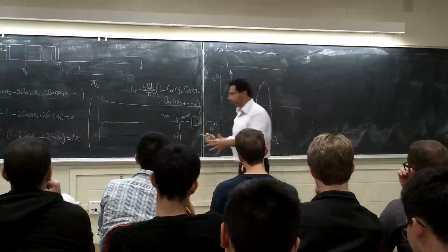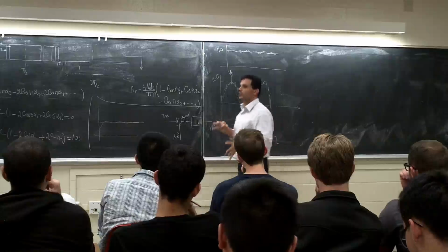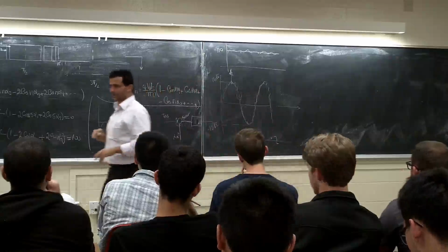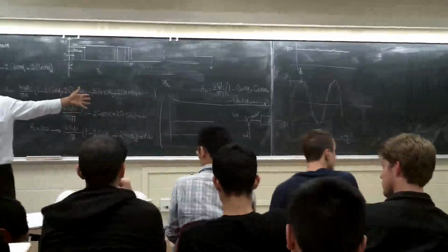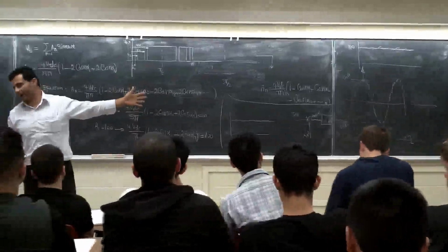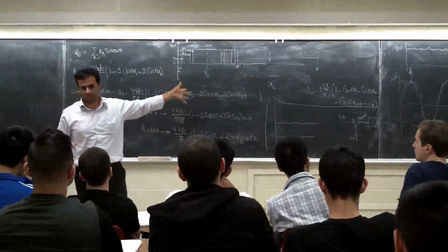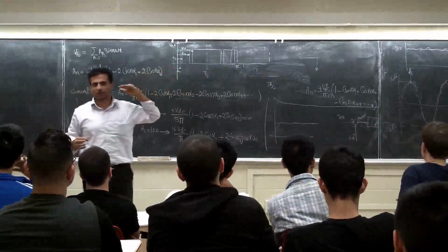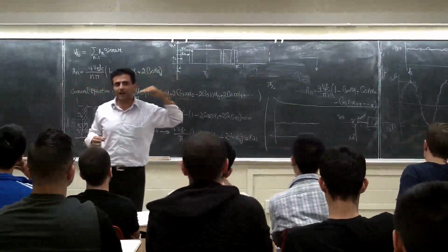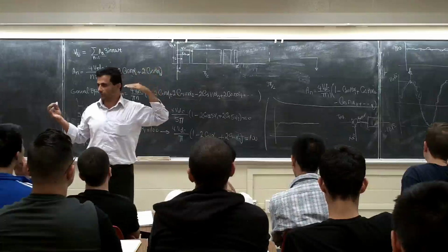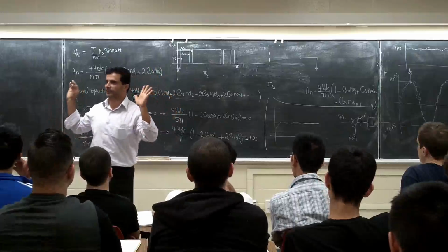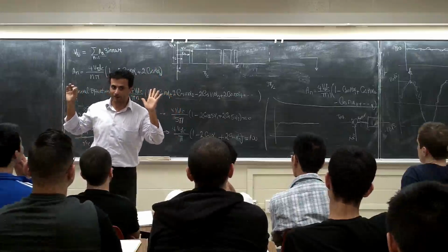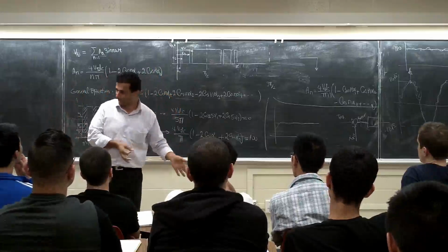The reference frame theory is going to take all of this to a new frame, which is going to work with either the maximum value of the sinusoidal waveform or the RMS value. We work with the maximum value. So you control the maximum value, and that's good, because if you control the maximum value, you can control the RMS value, and the frequency is automatically set. Why? Because you are sitting in the same car.